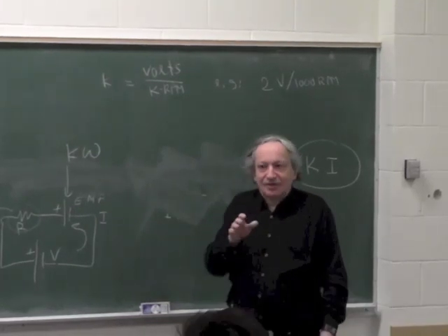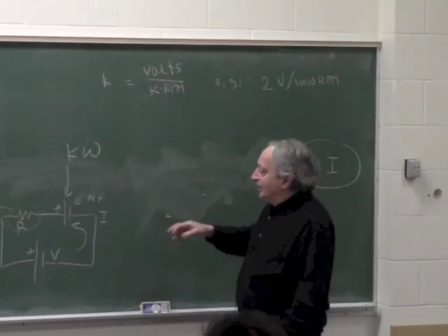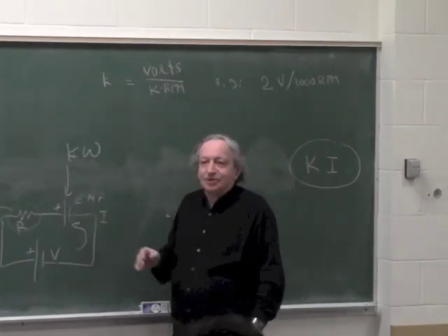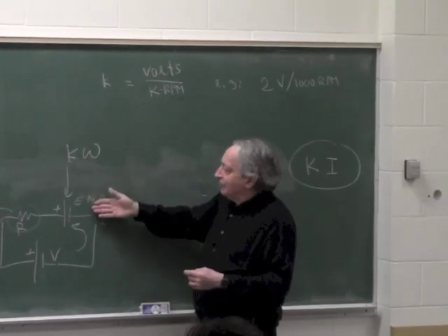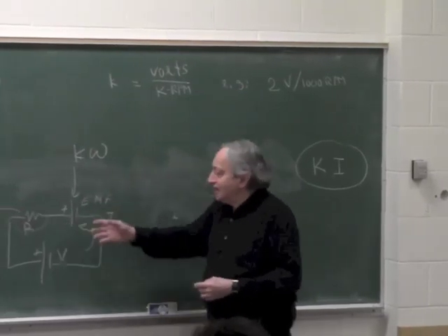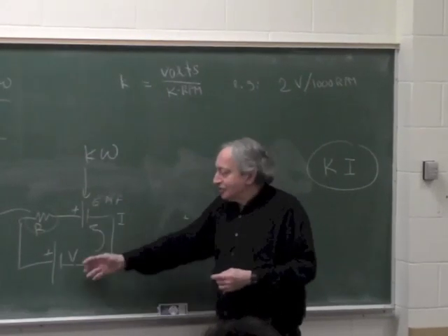So do you understand it intuitively why, if you change the voltage, the RPM has to change? Because the RPM generates a back EMF, and if there's no resistance, it's like another voltage source. So the voltage sources have to be equal.